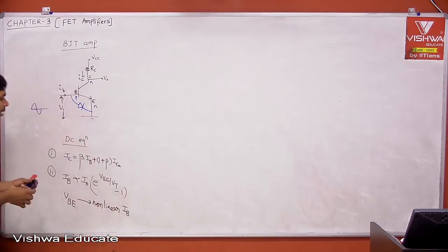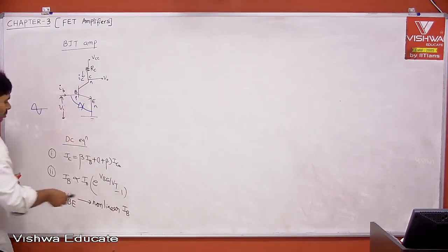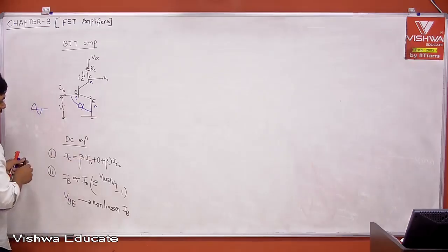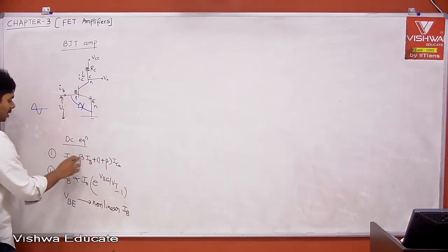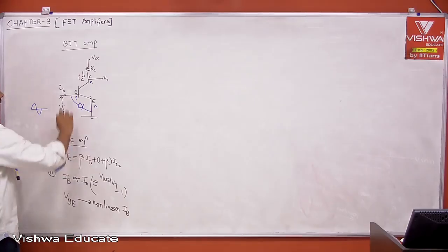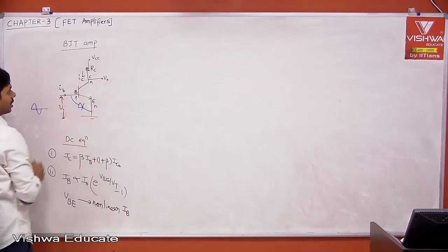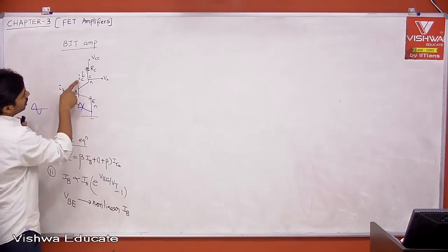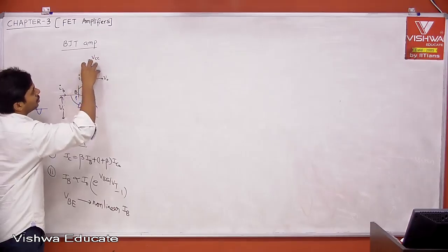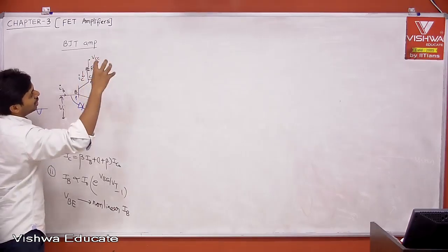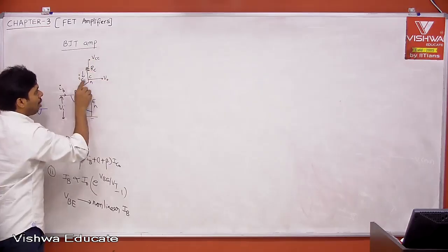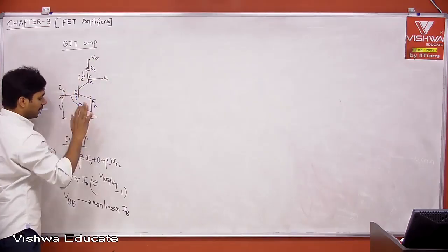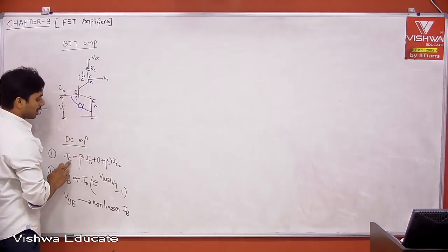When you get non-linear IB, what is the relation between IB and IC? I can say this is kind of linear. Therefore, IB to IC is linear. Then again, IC to output voltage is linear. Whatever output current you are getting, you pass through RC, and you get a linear relationship. Therefore, output current to output voltage is linear, and output current to input current is linear.